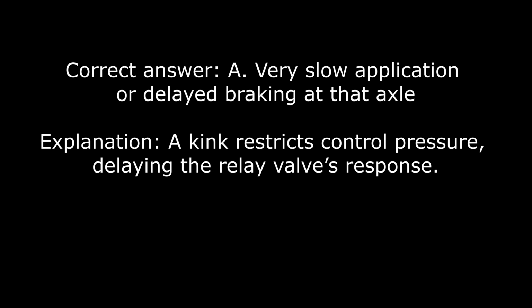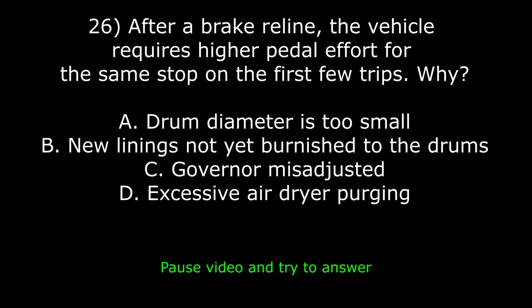Very slow application or delayed braking at that axle. Explanation: a kink restricts control pressure, delaying the relay valve's response. 26. After a brake reline, the vehicle requires higher pedal effort for the same stop on the first few trips. Why? A. Drum diameter is too small.